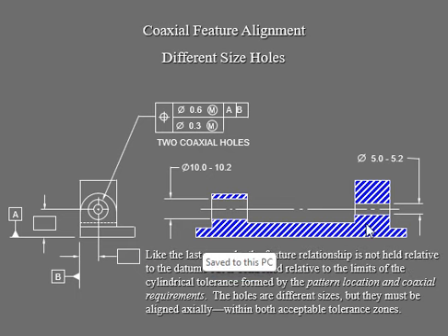And here, the most important thing you need to understand is the size of the hole. Look at that, it's different, okay? Size of the hole, look at this. They are different, and it says so here, one is this, another one is that. However, we are sharing the same position tolerance for the pattern, and also this 0.3, okay? Which is your tolerance for your feature.